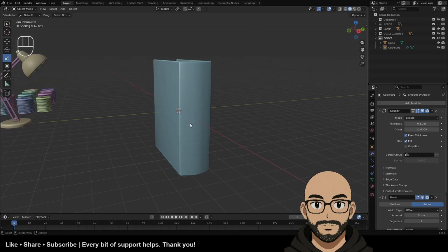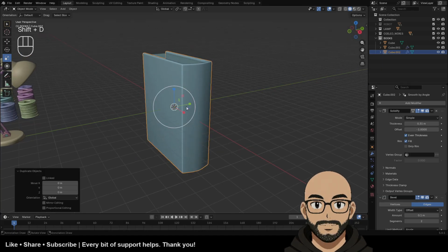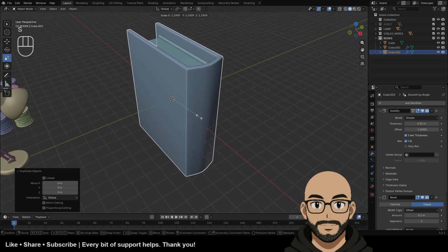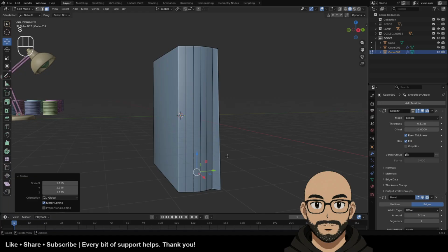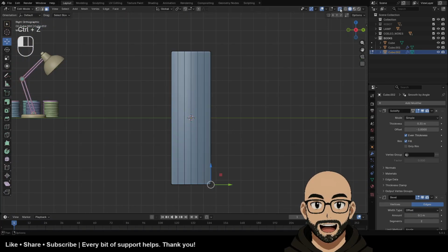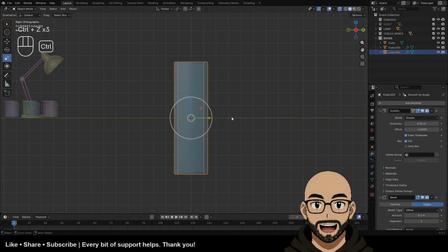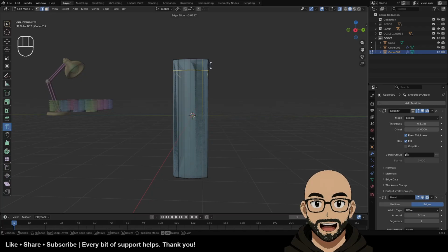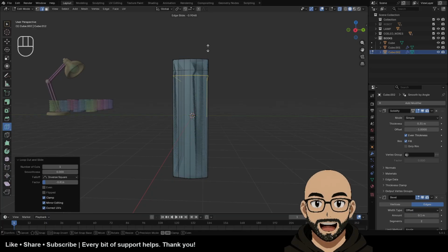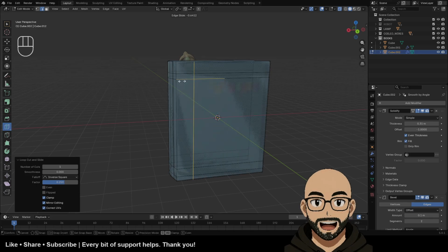So now all I want to do is create additional pieces on this. So I'm going to Shift D to duplicate this cover. From this cover, I want a slice, I don't want the rest of it. So we're going to X-ray. I'm going to add some edge loops across here. So I'm going to undo, back to where it's scaled. Now add the edge loop. Let's put an edge here, for example, and one down here, and maybe on the front.